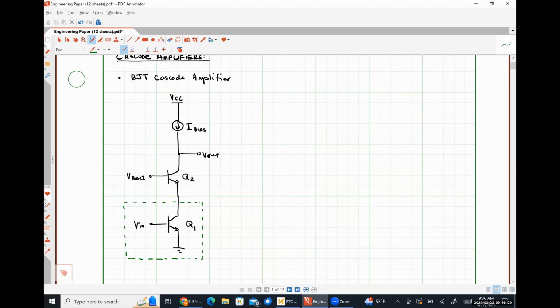So if we were to just worry about what I put in this green box right here, what would this kind of look like? To me, it looks like a common emitter amplifier. I haven't explicitly stated that my output voltage for this transistor amplifier is up here, but I don't know where else it could be, because the other pin is at ground and the other pin is our input signal. So we have something approaching a common emitter stage here.